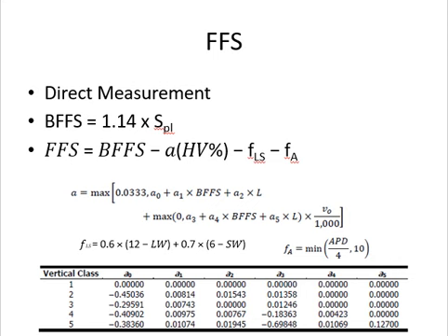For the A factor, you can see in this equation we have A0, A1, A2, A3, A4, A5, and we have L, which is the length, and we have V0. V0 means flow rate of your opposite direction. Now you have two directions, right? We did it in the last lecture as well. We may be doing the level of service for each one of them separately. So for this direction, you have to take this flow rate. For this direction, you have to take this flow rate here. Clear?